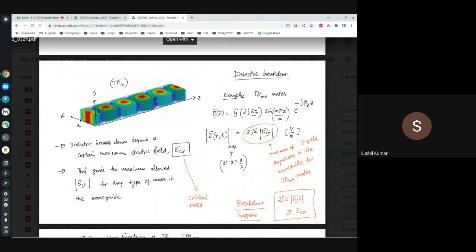In general, the simplest way to explain breakdown mathematically is that an electrical breakdown would be a critical electric field. It may be 10 to the 5 volts per meter. It may be 10 to the 7 volts per meter. So that's E critical. If your field anywhere in that dielectric is higher than that magnitude, then there will be some damage. And once it's damaged, it's often not reversible. We can't reverse that damage.